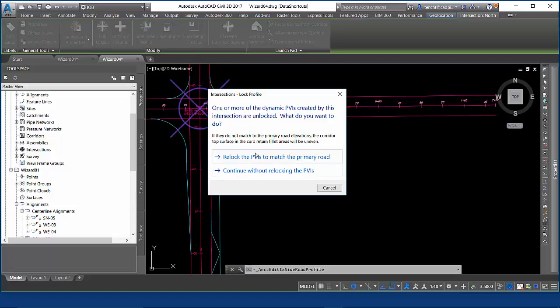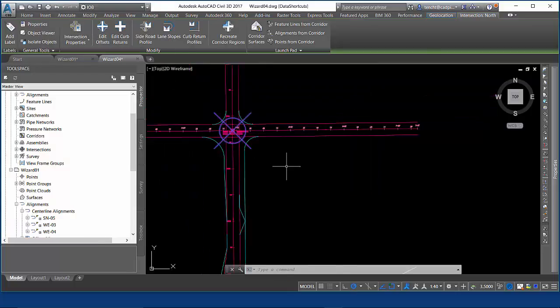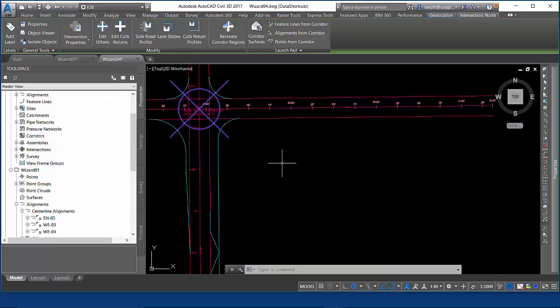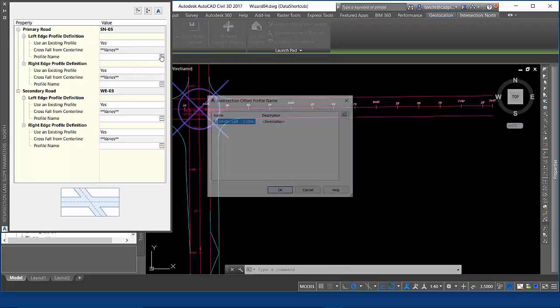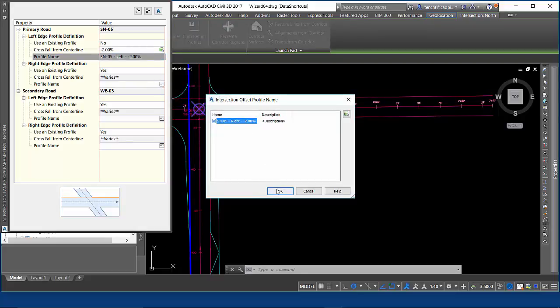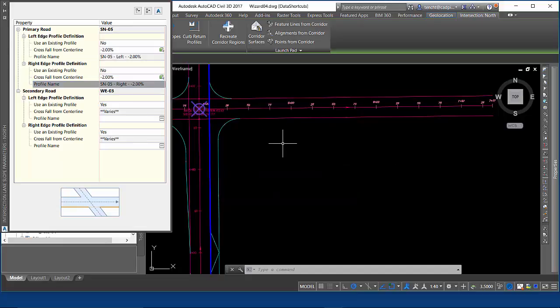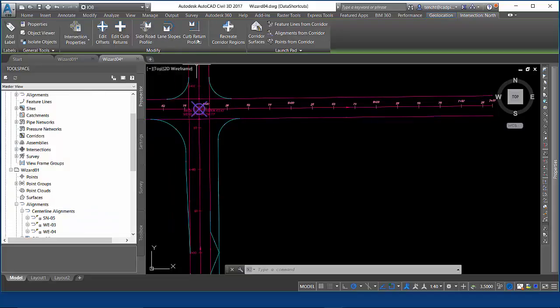Select it. Once again, just hit this box. You know what, I already made those choices and planned for those. Now we're going to do the lane slopes. My south to north, I already just corrected. So once again, we're back to, yep, there's my 2% left. My south to north, there's my right profile that I already created from the other intersection. These do not yet have. We'll just use our default slope control, and we're done with that vertical.